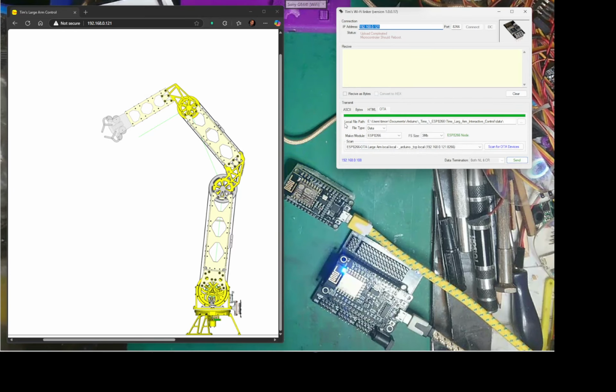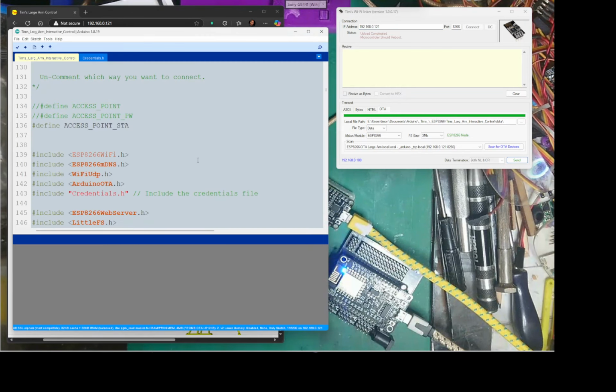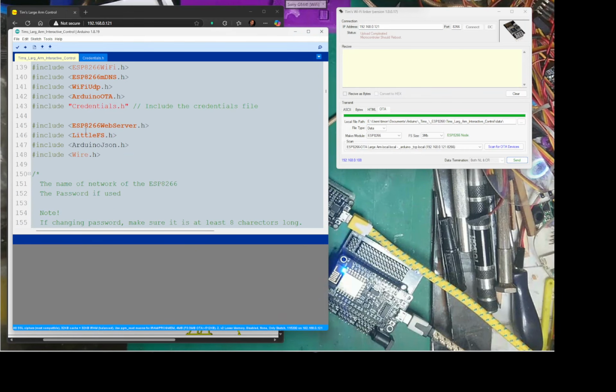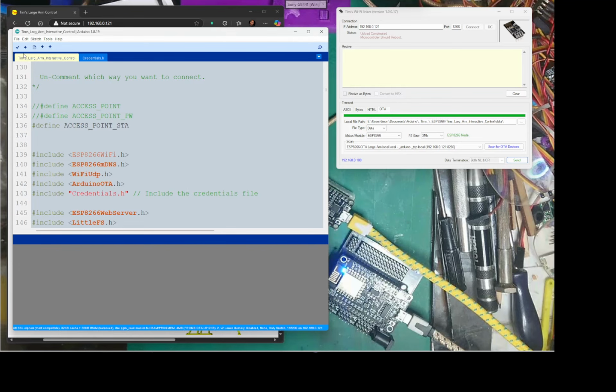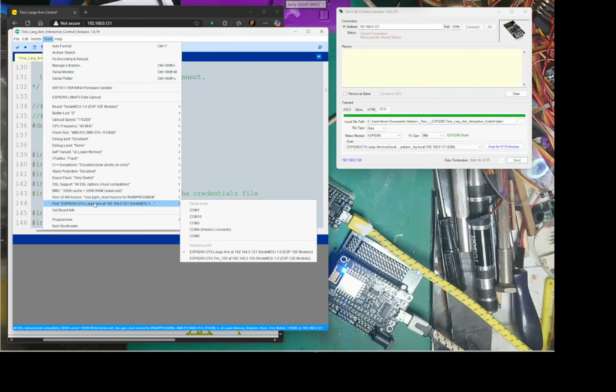And I also wanted to be able to actually upload the firmware. Now you can easily get the firmware from your Arduino IDE. So if I bring that back up again, when you actually use the Arduino to upload, you can use upload depending on your settings. It uploads to the port you've set, so it can do it through the Wi-Fi over the air, or you could use a COM port, what you plugged into.